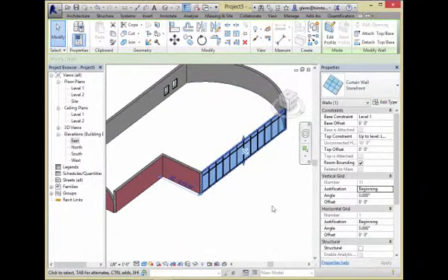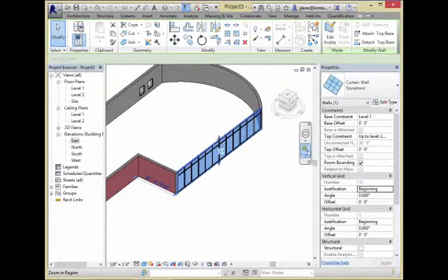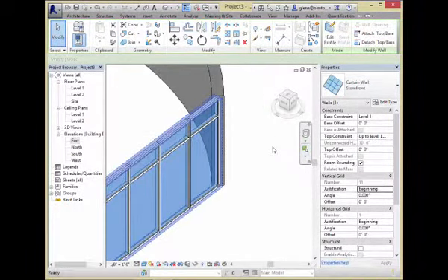If you have a panel size where the wall has turned out to be an odd increment of the panel size, sometimes you have these little leftovers at the end. All the panels are 5 feet long, but you have that extra 2 feet. So the question is, do you want to see that in terms of the whole panels justified to the beginning of the wall, the end of the wall, or do you want to sort of split the difference and have that 2 feet, 1 foot on one side, 1 foot on the other side? Yeah, you probably won't run into that too much in your design, but that's what that parameter is all about. You get the choice of if there's any left over where you want to put it.